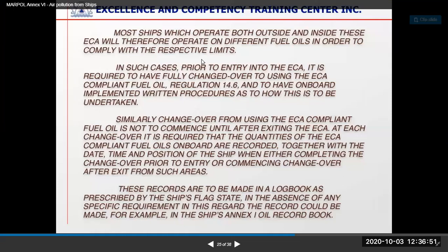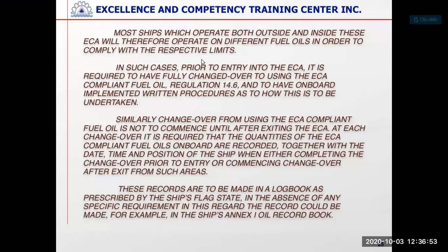Now, since we saw that we have different requirements for SECA areas fuel oil and outside SECA areas fuel oil. If you are operating outside special area, suppose in 2020, you will have 0.5% m/m fuel oil. So when you are going into SECA area like North Sea, you have to change over from 0.5% sulfur fuel oil to ultra low, that is 0.1% sulfur content fuel oil.